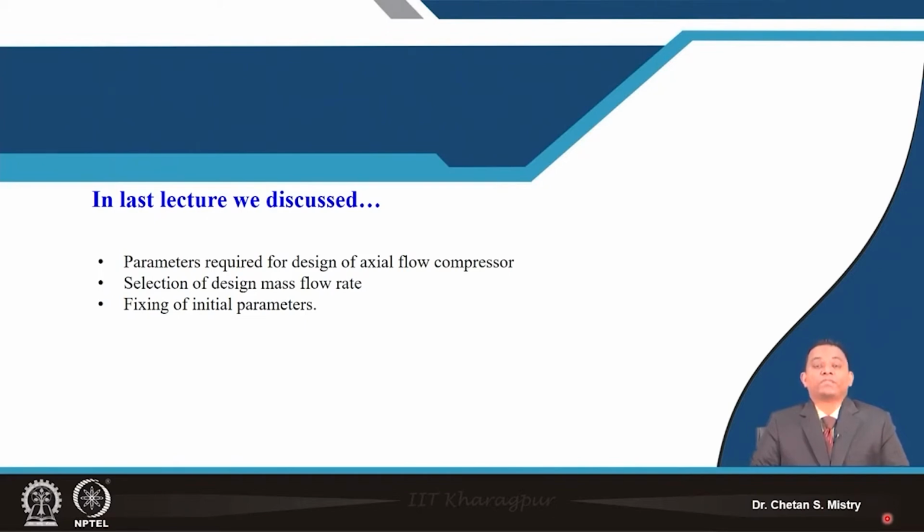For the initial stage, the pressure ratio is large and we assume the efficiency to be lower, because the flow goes transonic in that region.